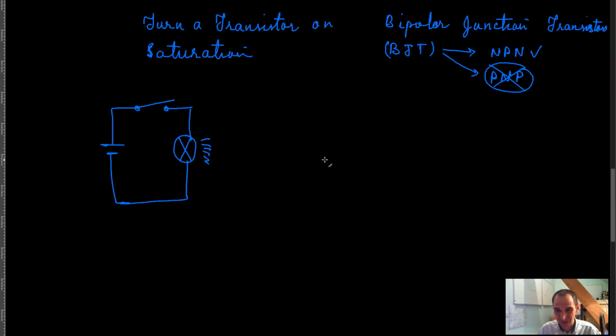So that's basically how you do this. Now, in case you didn't understand my explanation, that's how it goes. Essentially you have this transistor over here. This is the base of your transistor, and this is the collector, this is the emitter of the transistor. So base, collector, and emitter. This is an NPN transistor, so you connect this emitter to the ground, which is your negative supply. The load over here is connected to your collector, and then this goes to the positive supply, right?